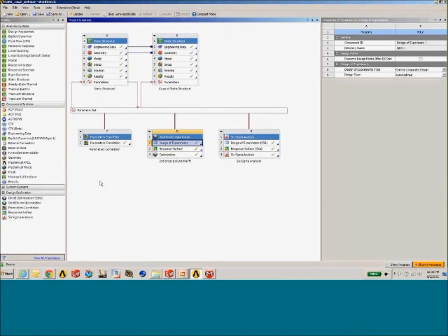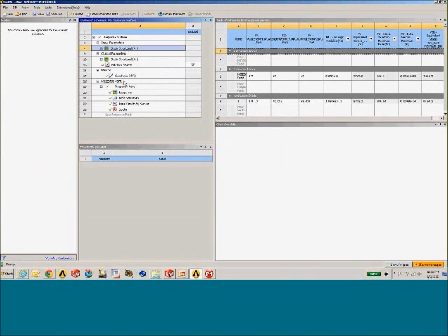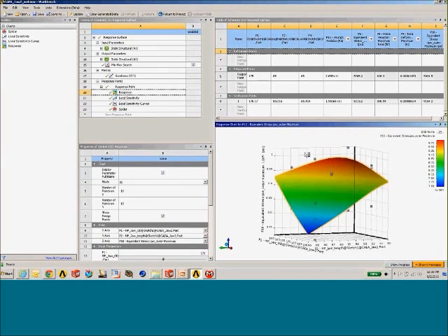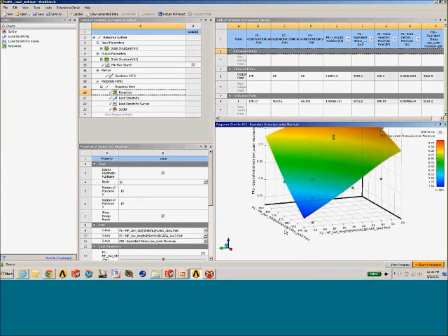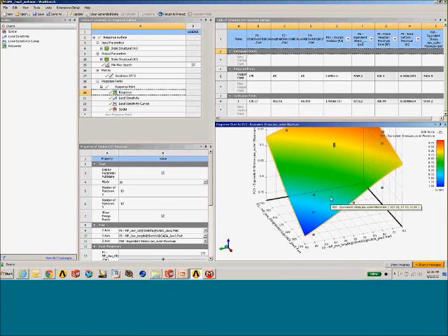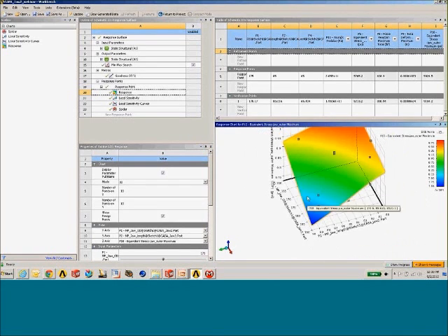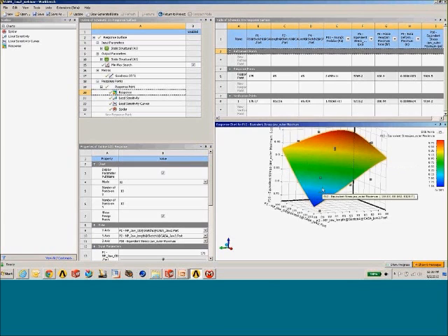Having done that, we can return and now look at the response surface, or basically map the response of the output parameters to changes in the input. So we can look at 2D or 3D responses where, in a 3D case, we can map the response of change in two input variables to one output variable. You can set up multiple response plots. You now have polynomials that relate the response to changes in the input.